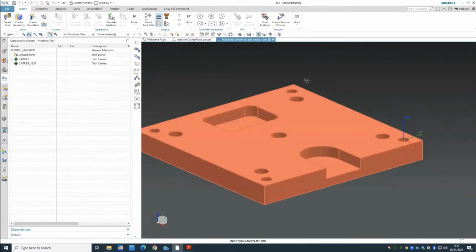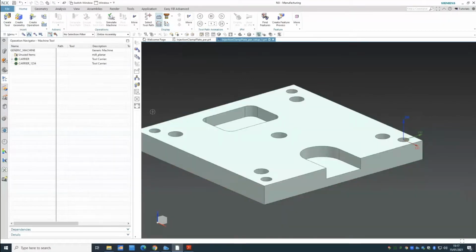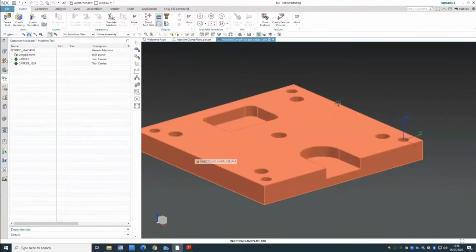I'm going to have the whole design as a full pocket because I want to do a face milling on that. And also each of these big holes is going to be considered as one pocket, and the smaller holes as a different pocket. So I'll put them into groups, so the machine does them in different sequences. For instance, first I'll do a face milling on the top. Then I'll do the operation on these. So it would be one pocket on the top, two pocket, these big holes, third pocket, and these smaller holes, fourth pocket. So these are groupings.